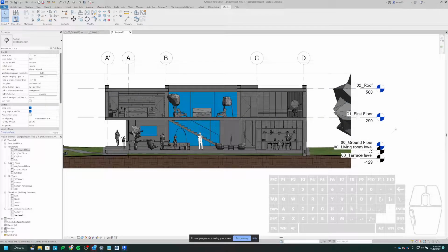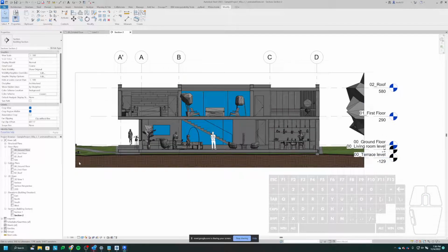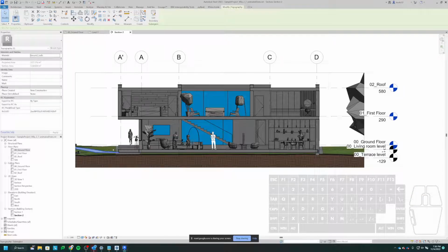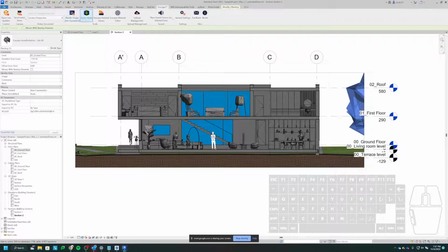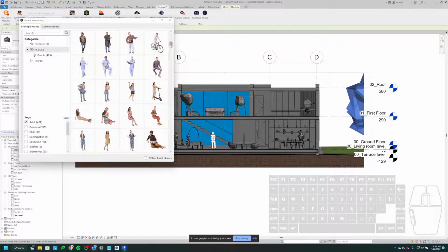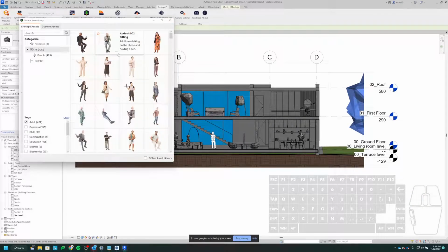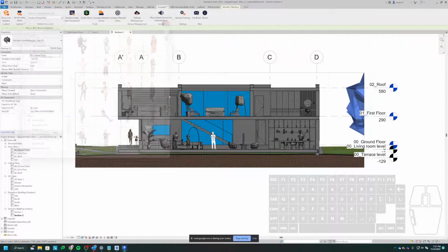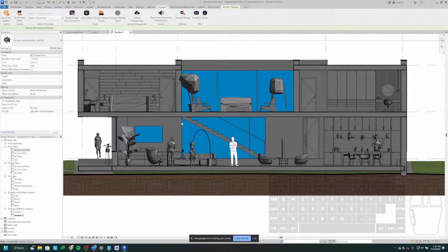We're going to want to get rid of possibly the topography. So that would be the ground here. Or we could maybe keep it in, we'll see. And then maybe some of these Enscape assets. The Enscape things by default that you bring in from the asset library here, so all the people and stuff, they look good in 3D and Enscape, but in Revit views they look really, really bad.